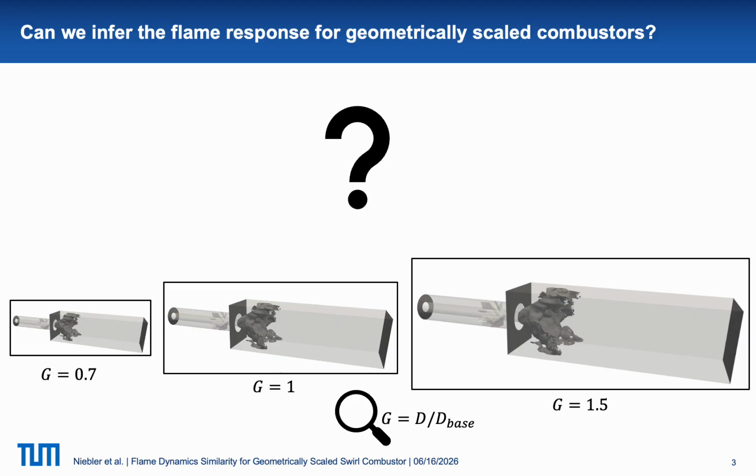On the other hand, downscaling here denoted by G.7, basically stands for cases where we have an operating family and we want to transfer knowledge from this baseline family to a smaller, or maybe first designs of a smaller family, which inherits information from this baseline configuration. With this, we really scale all the length scales of our combustor by the geometrical scaling factor G.